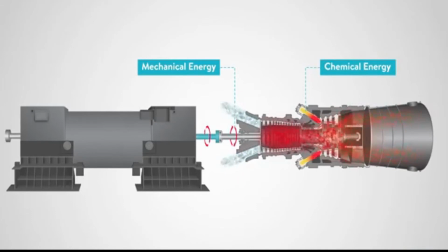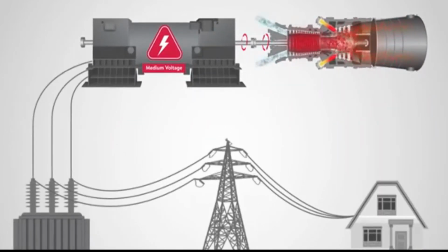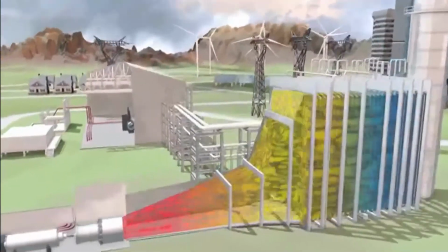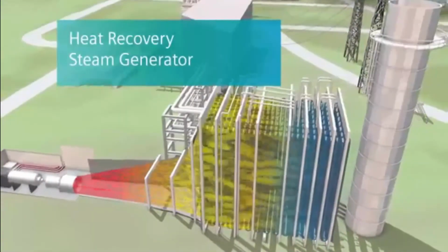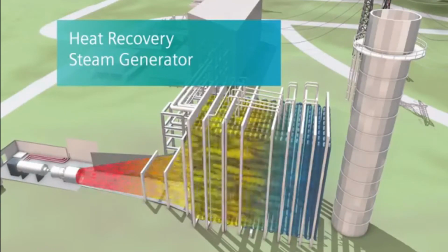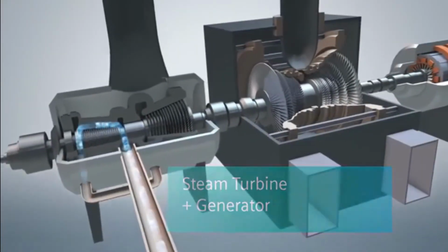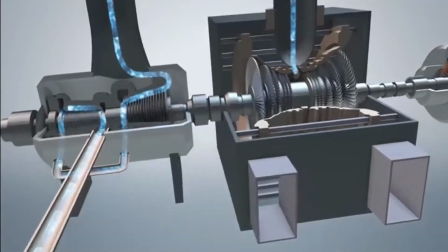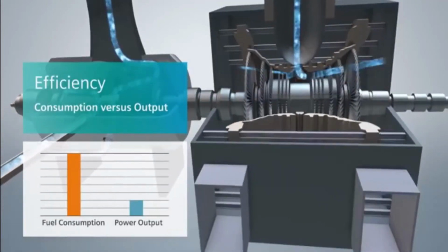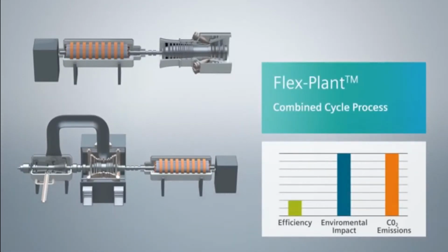The gas turbine plants are built with multiple units of 10 to 250 megawatts each, with a possibility of adding combined cycle thermal generation on every pair of turbine units by using the exhaust gas temperature reaching 540 degrees Celsius. The advantages of gas turbine plants include low capital cost, quick plant construction, waste heat recovery possibility, quick engine start for peaking duty, and suitability for small remote communities. The disadvantages include high fuel cost and environmental emissions issues.